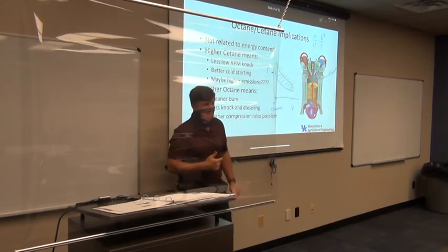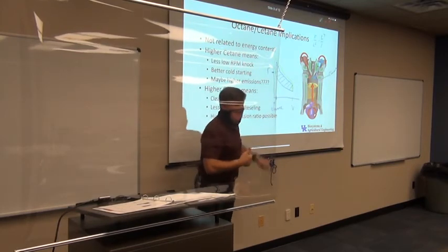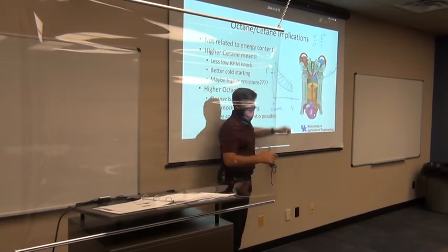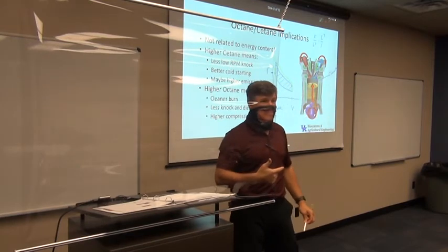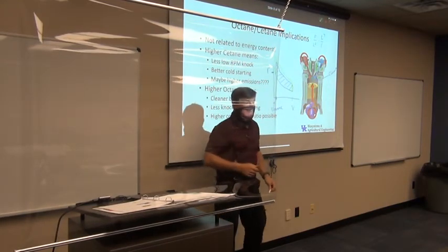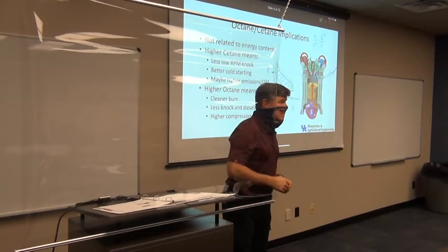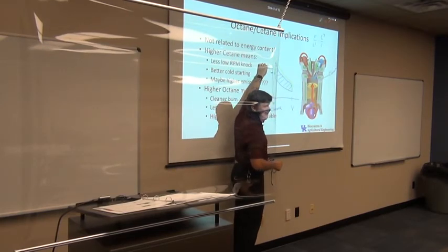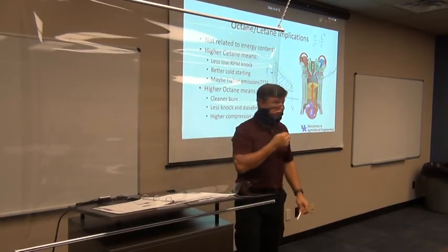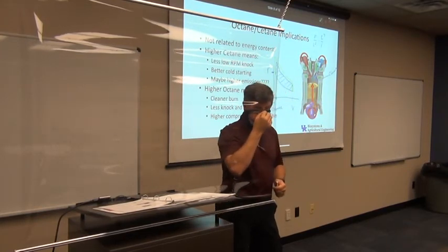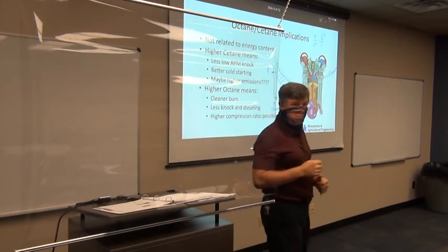What did I do with my auto ignition pressure? If my auto ignition pressure was sitting here, what did I do? I took my pressure above my auto ignition pressure. What does that tell me about that low octane cheap fuel that I was putting in that engine before? Is it going to work? No. What am I going to have to do? I'm going to have to buy higher octane fuel to get that auto ignition pressure higher than that corner, so that the fuel doesn't ignite when I don't want it to. So, going back to that initial question, do I get more power out of high octane fuel?